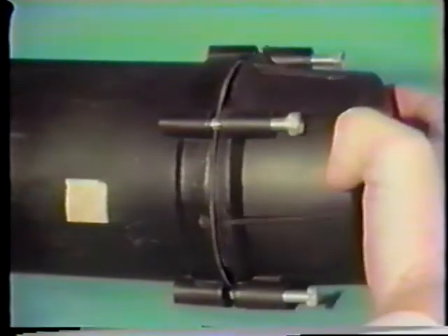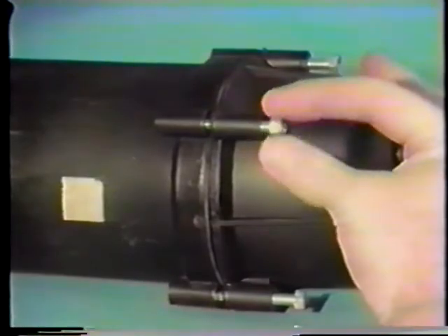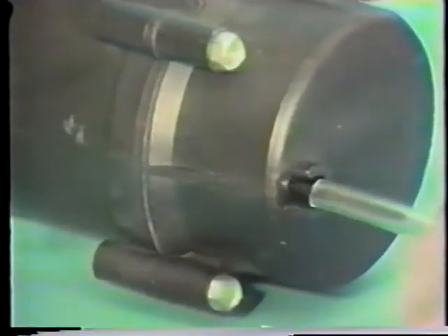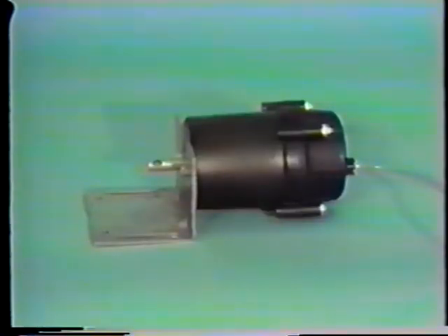The actuator housing holds the spring and the actuator shaft, which is attached to a diaphragm cup. The diaphragm is molded in a cup shape with a sealing edge to conform with the outer edge of the actuator body. When assembled, the actuator cap is bolted to the actuator housing to form an airtight seal in the cap end. Air pressure is provided at an entry point in the actuator cup, placing air pressure on the diaphragm. This pressure transfers its force to the diaphragm cup, compressing the spring and extending the actuator shaft.